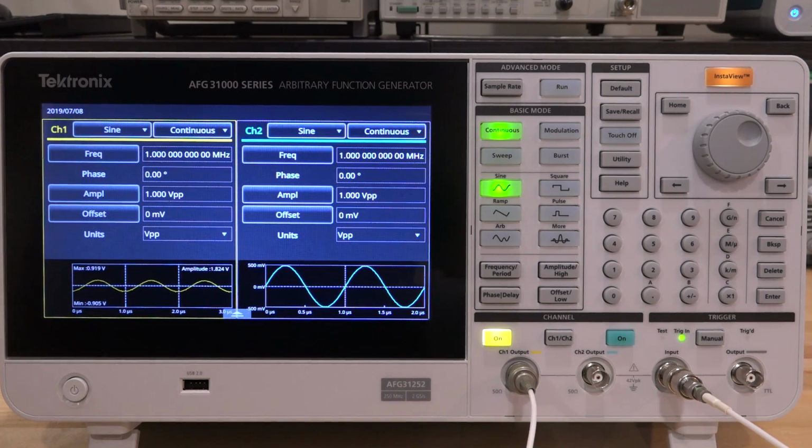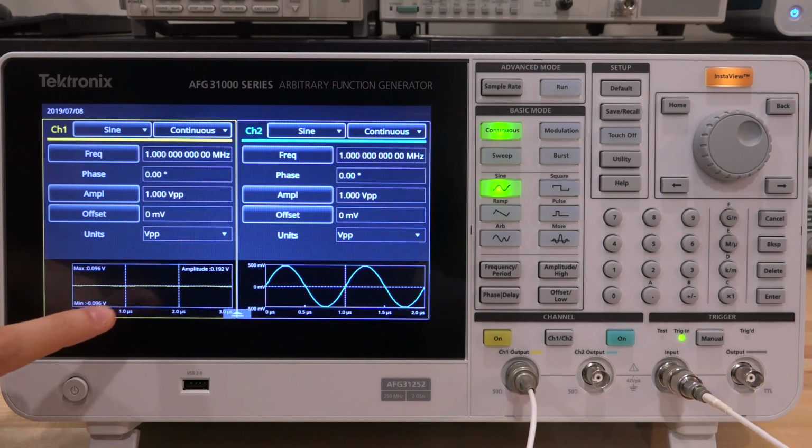So right now it's settled, and I'm going to disable the output here, and you can see it does it again. Now you can see this is measuring live what is coming out. But let me connect it up to a test setup that I've built that has a very problematic impedance at the DUT, and see if this guy can actually measure that and give us the correct waveform.